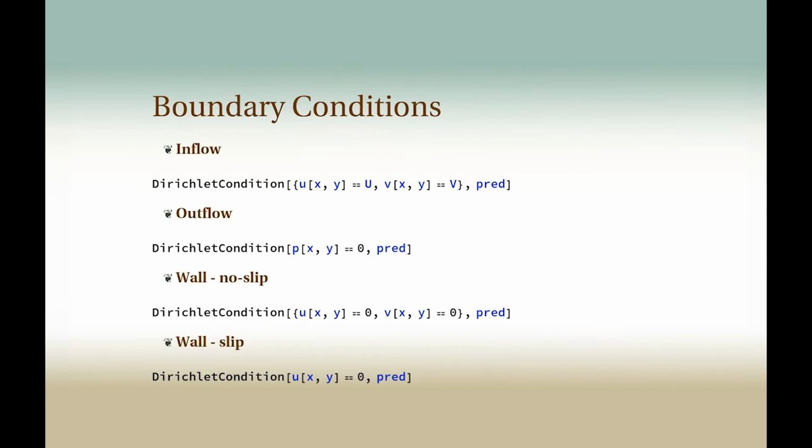Boundary conditions. So you note that in this case, we use Dirichlet conditions for the boundary conditions. And the reason is that because we've only now started adding these PDE components for fluid flow, we haven't had a chance yet to make absolutely sure that the boundary condition setup that we'd like to have works for all types of fluid applications we'll want to do in the future. So think about turbulent flow or things like that.